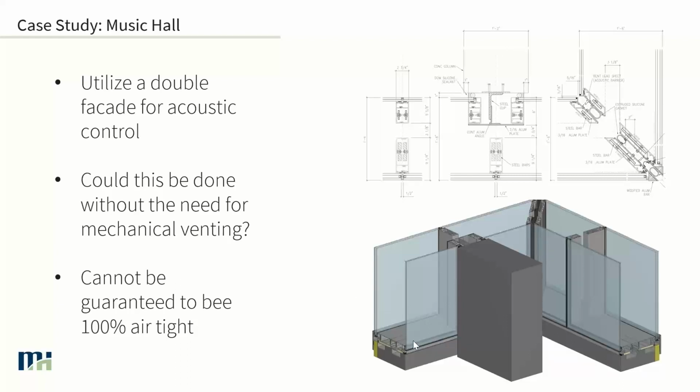You can't necessarily guarantee that this system will be perfectly airtight. So typically they would do mechanical venting, but if you want to avoid that, what are our solutions? First and foremost, what is the risk? What would happen if warm, moist air got into that cavity space?